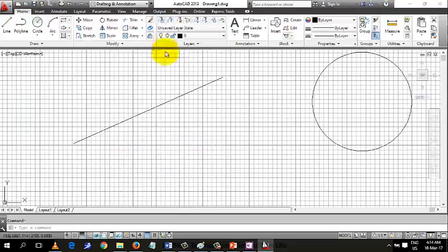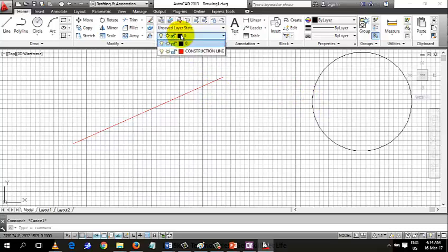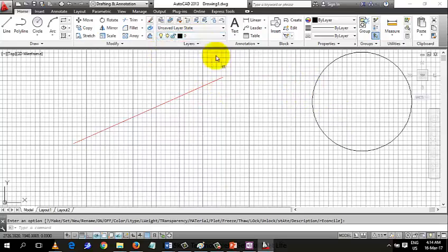Then close. Please don't worry if you don't get this. We are still coming there. So I can select this drawing and change the layer to construction line. So you can see that this is on red, this is on black. So I can decide to turn off this construction line so that I can see only the red. You can see that it is gone. Then I can decide to enable it back. So I only did this to explain to you the function of layers.